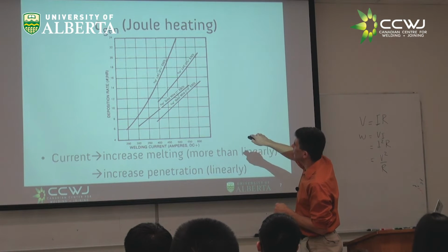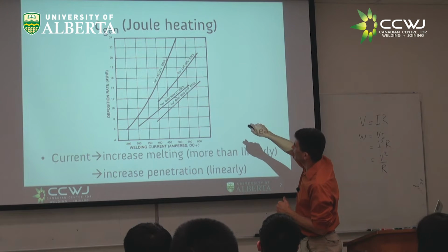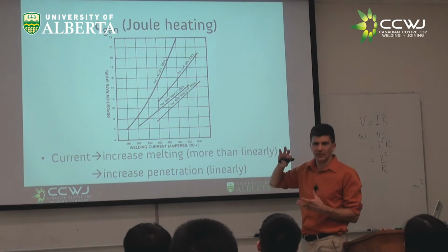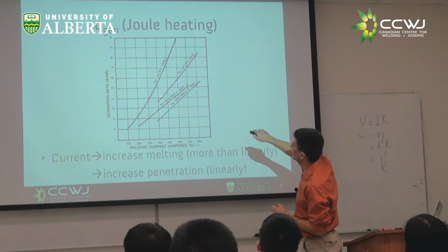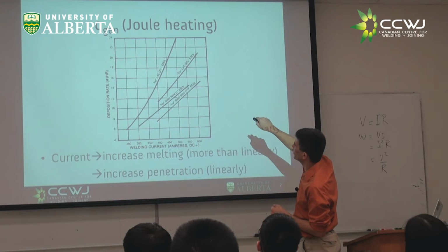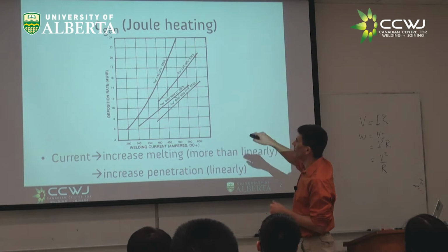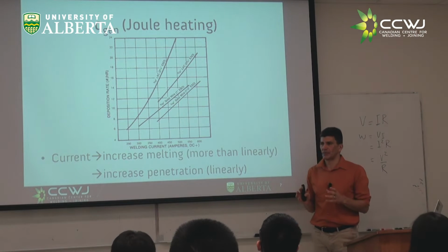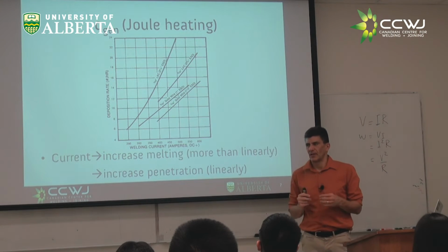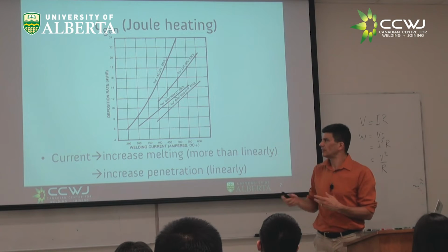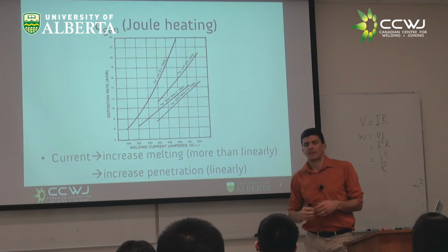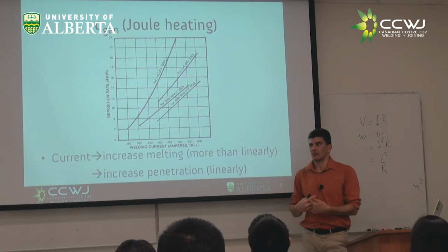If you look at this 332 wire here and there, here you have 1 inch stick out. In submerged arc welding, right, everything is bigger. And here you have 2 1/4 stick out, you have more deposition rate. Right? It's Joule heating that makes the difference. I'm a big fan of, this is called extended stick out, right? I'm a big fan of extended stick out.